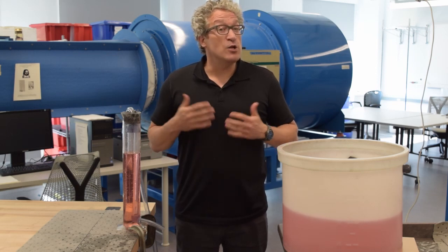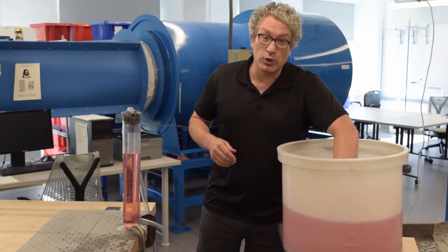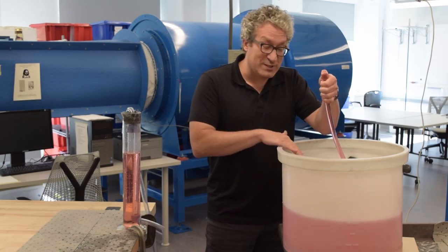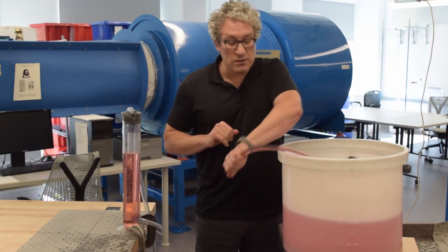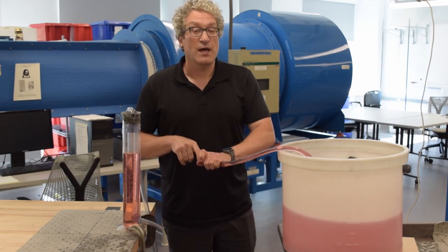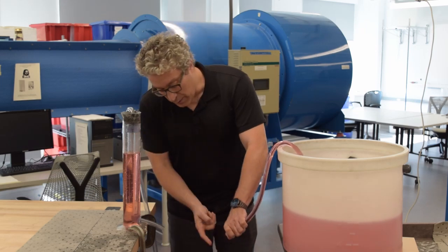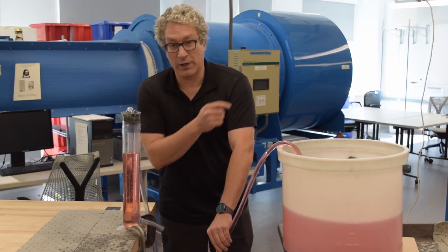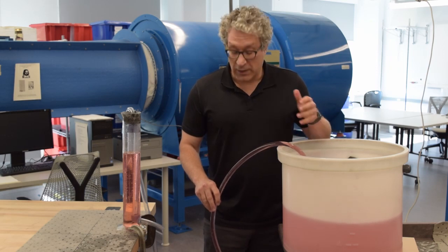So, a siphon, at least knowing whether it'll work or whether it won't work, is a simple application of the hydrostatic equation. Anytime we look at static fluid in a reservoir or in a tube, the hydrostatic equation tells us that the pressure goes down as we move up in elevation and goes up as we move down in elevation. Regardless of where I move this tube, the hydrostatic equation always tells me what the pressure will be at the end of my thumb. And that tells me whether water will rush out or rush in when I take my thumb off. As long as I put the end of this tube below the level of this reservoir, I should be able to pull fluid out of this reservoir into this system. And again, this is now something I can do without a valve, without a spigot, or without a pump.